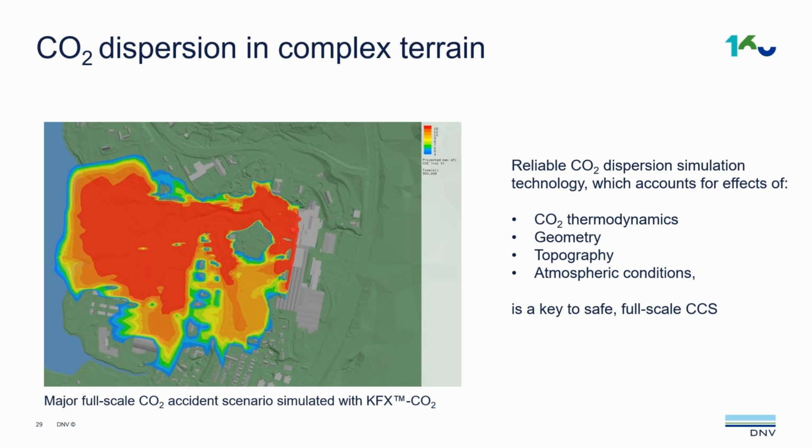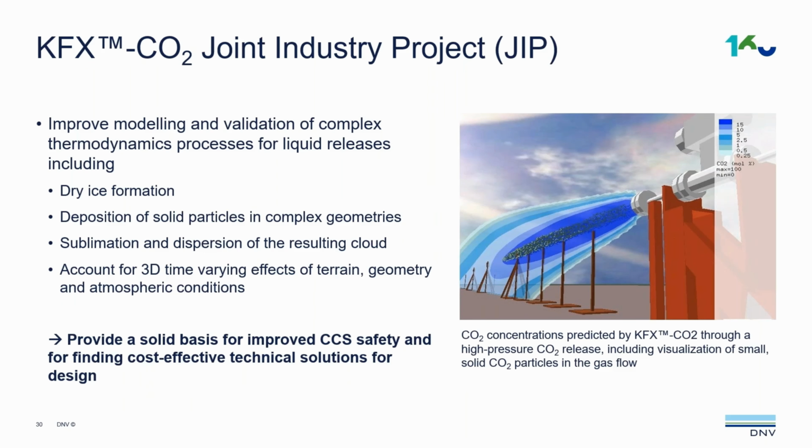to safe full-scale CCS. And that is one, at least, of the reasons why we are currently running a KFX CO2 joint industry project together with Equinor and Total Energies. We aim to improve the models in KFX so that it can model accurately dry ice formation, deposited CO2 solid particles on the ground, sublimation of CO2 particles in the gas cloud, and the resulting dispersion, all taking into account topography, geometry, and of course, atmospheric conditions. This JIP started in 2019 and will conclude this year.